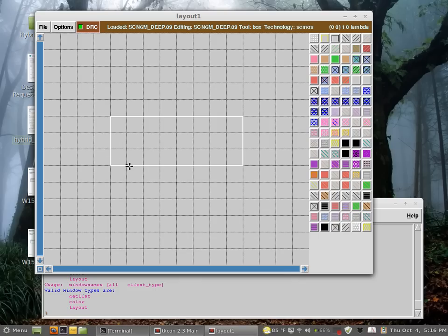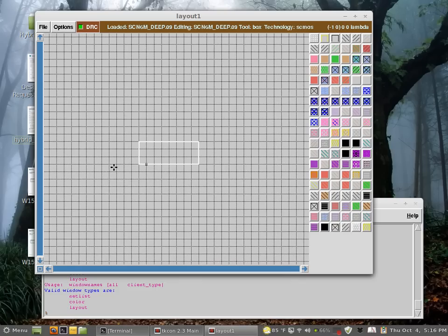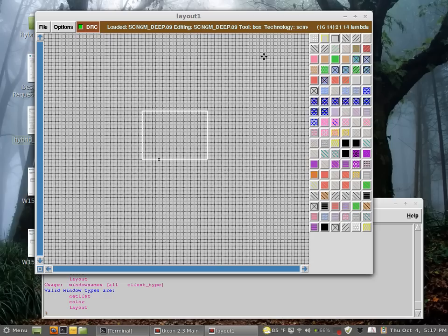Alright. So, let's start. So like I said before, we already have a P substrate. I don't have to specify it. It's already there. You can imagine all this gray stuff is a P substrate. So what do I have to do? First, I have a P substrate, and then what do I need to do the PMOS? Yeah, I need the NWell. So let's do that first. I can't tell the size at first that I'm gonna need. So let's just make it this big, okay?